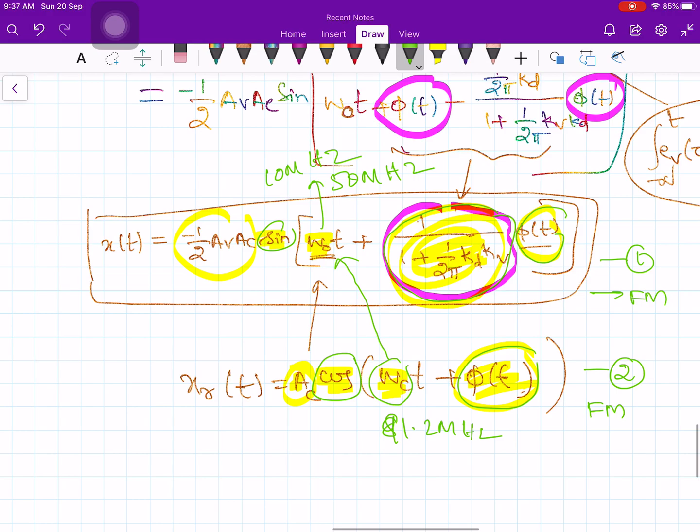Okay, that constant was missing in equation 2. So the FM signal, or the PM signal, at the input was sin(omega_c t + phi(t)). Of course, we may have different carrier frequencies, but the carrier frequency is of no consequence, because the discriminator will be designed to operate at the carrier frequency of the input signal. So it doesn't matter for the discriminator. If you used the discriminator directly, it would have been designed around omega_c, that's it. So the carrier frequency is not an issue.